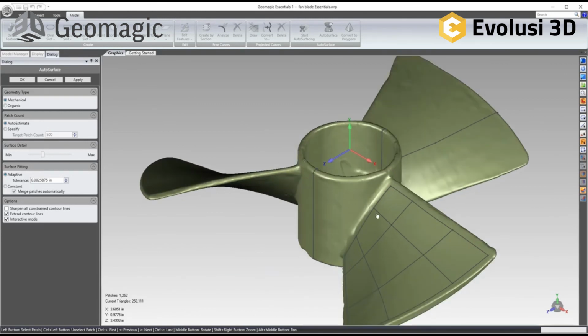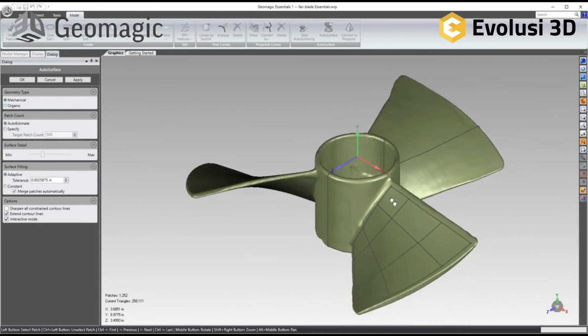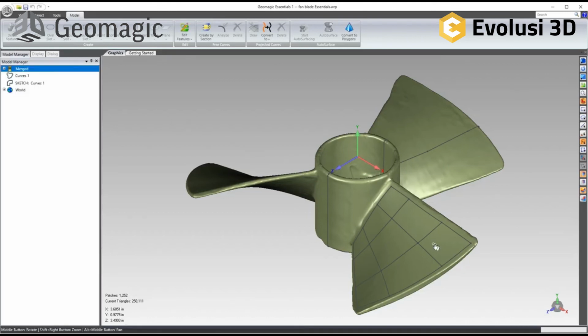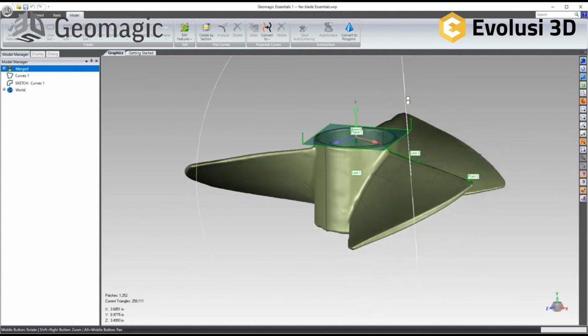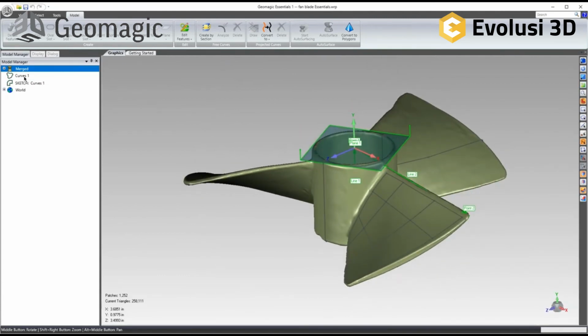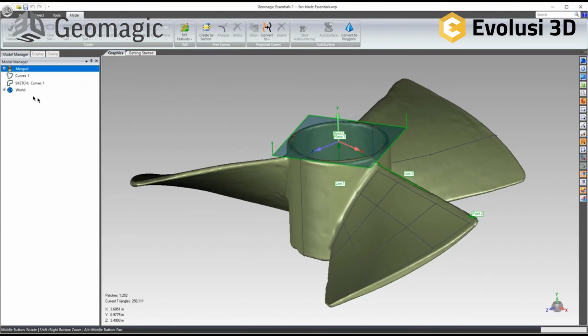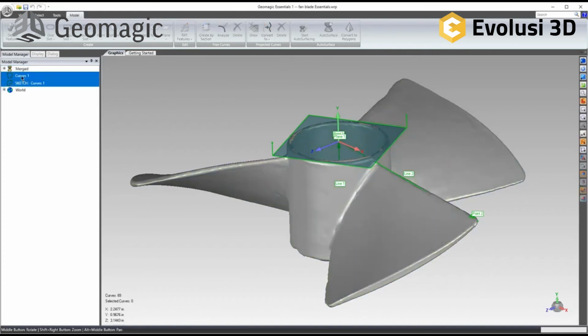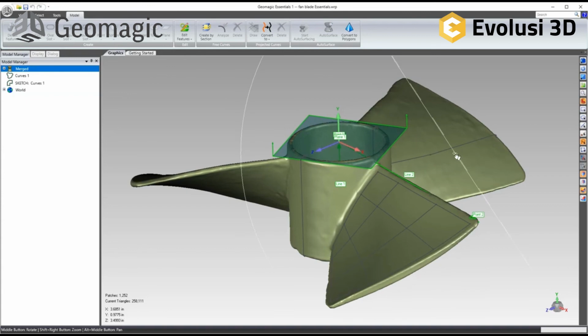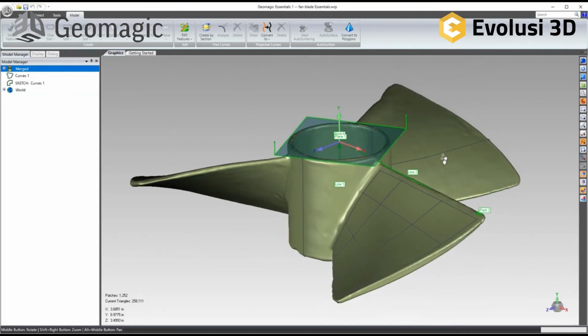So now the auto surface is finished. So you can see the curves, the CAD solid, well, it's a surface, not a solid, and the features. So I can write all of these to an IGES file and send them over to Solid Edge. So if I grab all of these, I can save them out to an IGES. So that's the next step, is to go ahead and save these over to Solid Edge.